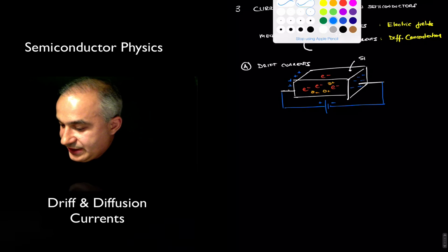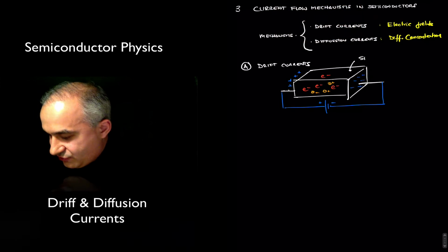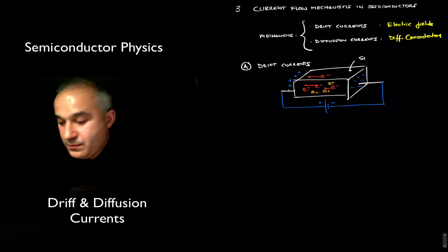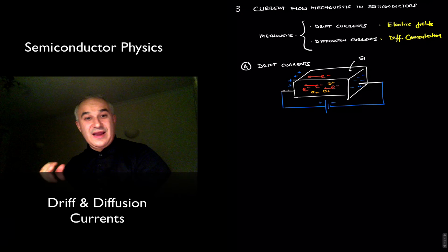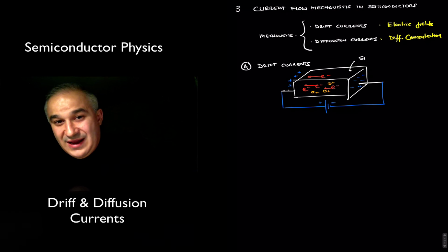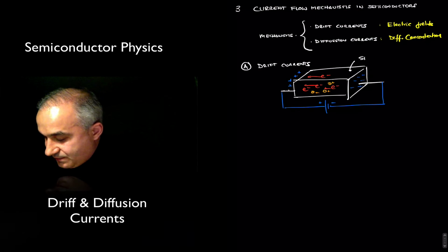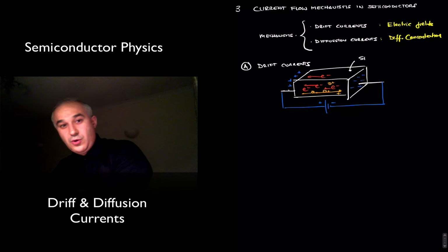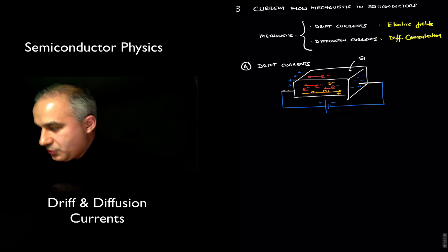Well, what we're going to see is that the electrons are going to start moving. Movement of charge causes current. Similarly, and those are electrons in the conduction band, you're going to have movement of electrons in the valence band, which are also moving this way, but that looks like a positive current going the other way, right? The holes being attracted to the other side.